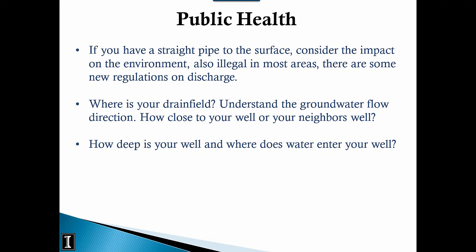But again, going back to the New York example, we ran into a number of wells up there where the casing was only 13 feet below land surface, and that stopped. And even though some of these wells were 80 or 100 feet deep, there's only casing to 13 feet. After that, it's an open hole. The bedrock acts as its own casing because it's solid rock, and you're taking advantage of the fractures so that you can get water into your well with a bedrock well.